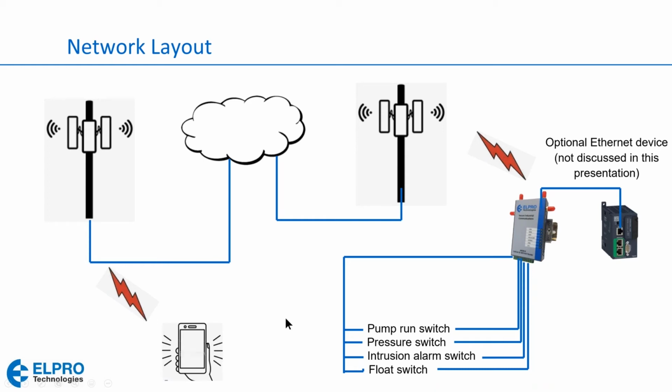So very powerful. You can get all kinds of alerts. Any type of switch can be wired into this cell modem. Now we're looking for just a dry contact, so just a voltage-free relay, and that could be triggered off of anything. That could be humidity, temperature, level. That could be chemical composition. There's all kinds of industrial switches for any type of application out there.